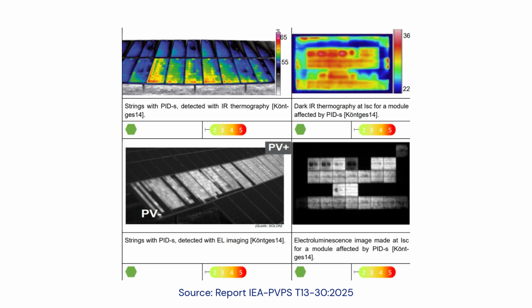The polarization degradation effect causes instead a significant reduction of short-circuit current, open-circuit voltage, and power. Polarization degradation is thought to be fully regenerated by reversing the polarity of the bias potential. In some cases, material degradation of the modules through corrosion and delamination occurs associated with excessive leakage current. Up to now, safety problems directly related to the degradation have not been reported, but hot spots and corrosion caused by the strong cell mismatch may cause such safety issues.